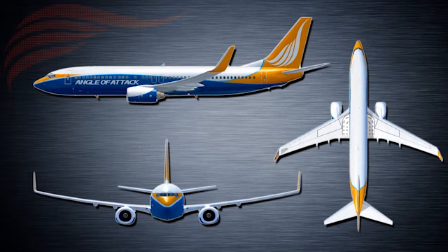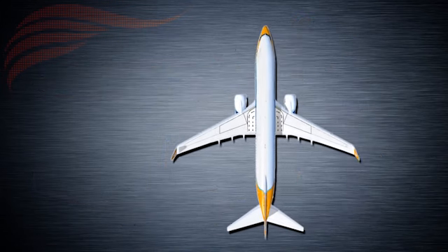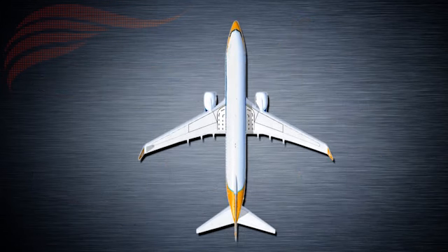There are two groups of flight controls: primary and secondary. Secondary flight controls are covered in the secondary flight controls lesson. The primary flight control surfaces and their direct effects are elevators, change in pitch; ailerons, change in roll; and rudder, change in yaw. An aircraft is free to rotate within the three axes and will always turn about its CG, or center of gravity. The tendency to do this is known as a turning moment.